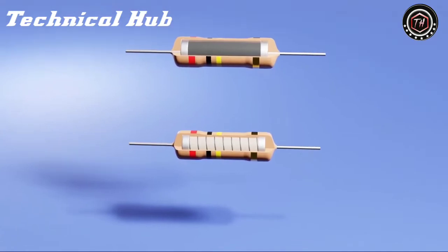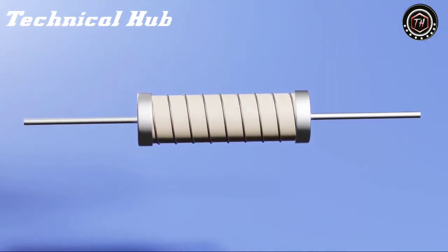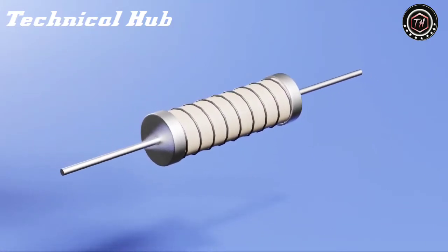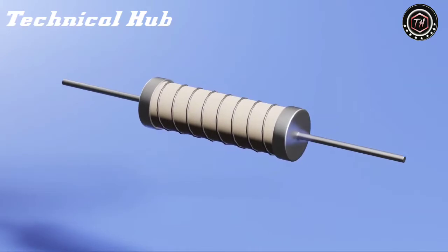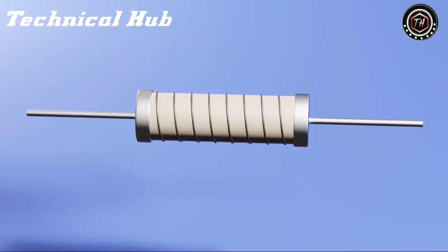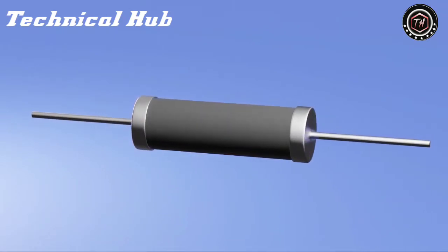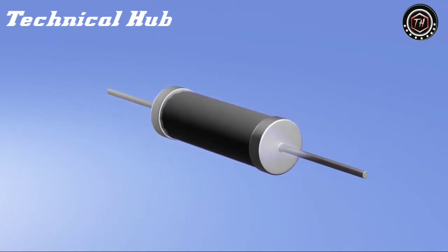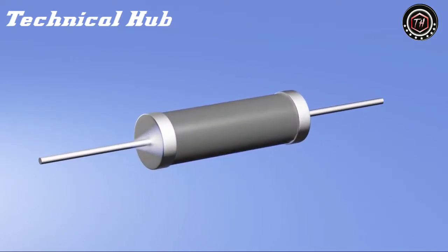The first way is using a nickel wire wound in a ceramic tube, which by the way is an insulator. In this way, you can control the total resistance modifying the length of the cable, but maintaining a compact size. The second option is using a composite material in a defined volume, but that by varying the elements that make it up, you can vary its coefficient of resistance, and therefore the resistance of the resistor.